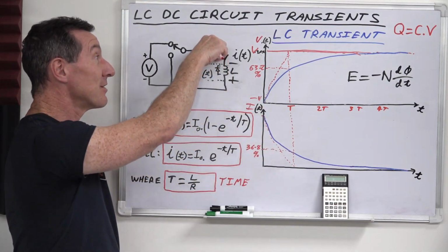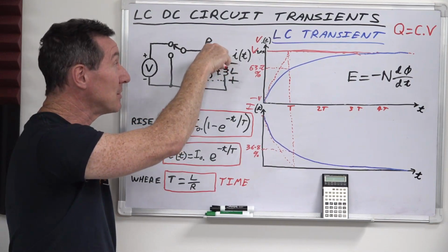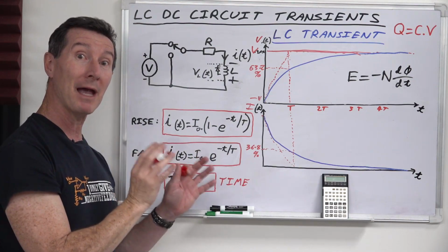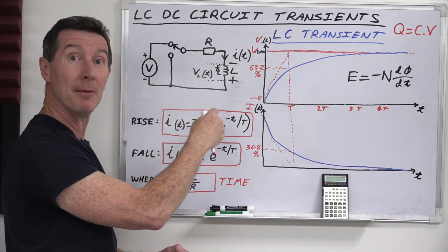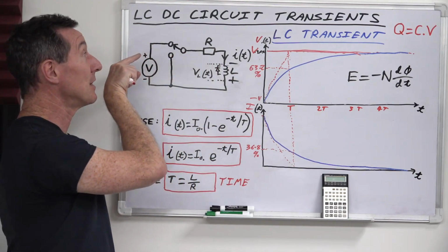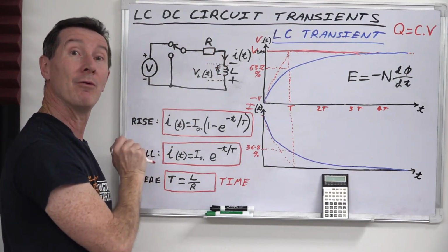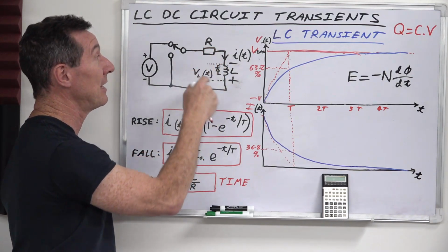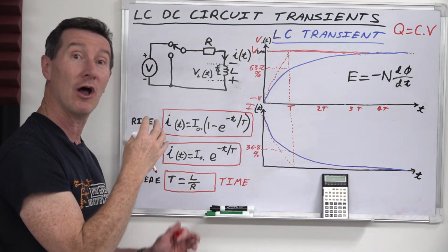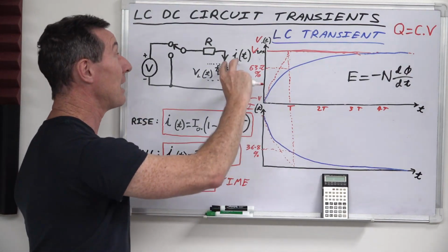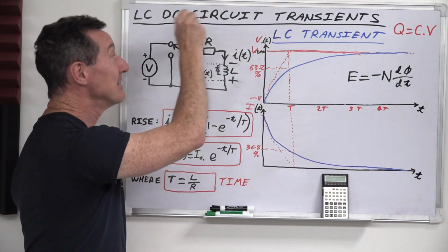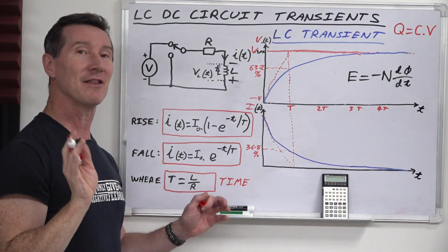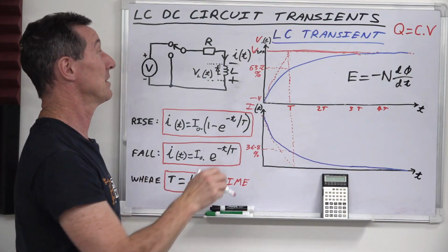The current is still positive, because as I said, it still flows in the same direction, which is opposite to what the capacitor did. When we're charging the capacitor, current flows in this way, but when we're discharging the capacitor, it flows back out this way like this, because the voltage is still like this. Inductors operate opposite. They flip the voltage like this and current still keeps going in the same direction. Not really intuitive, but that's how the physics of collapsing magnetic fields actually works.